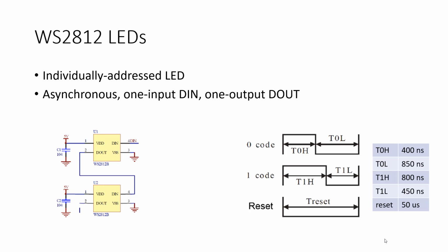Okay? So to program one LED, you're writing 24 entries into this RAM, which is a script that the RMT will run through and use to drive the pin with that sequence of bits. So every time you write one LED, you have to write 24 entries to this RAM that tell it how to send the color out to that LED. You guys with me? To each LED in sequence, as they're connected in series.